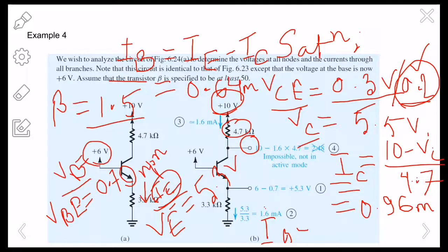If you test an NPN BJT using a multimeter to find the beta, you'll see the beta is around 150 to 250. But if you place that BJT in a circuit that is working in the saturation region, you will see that the beta is reduced to a very low level. It gets below 80 or 50. So the thing you see here is that beta is actually reduced in the saturation region.